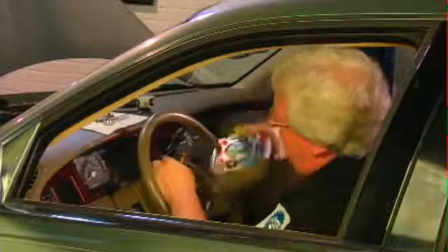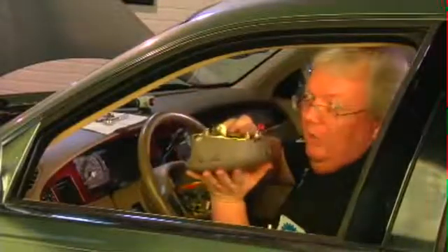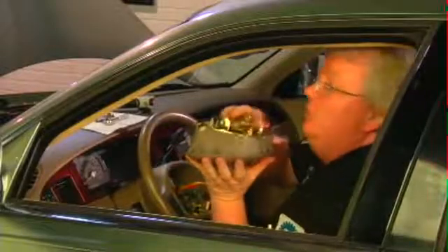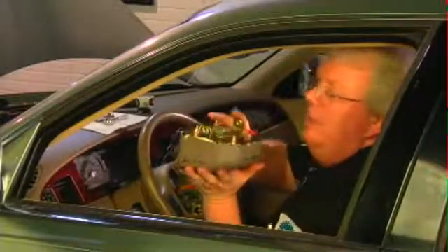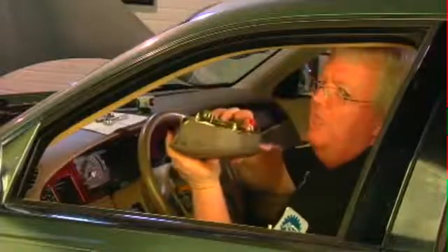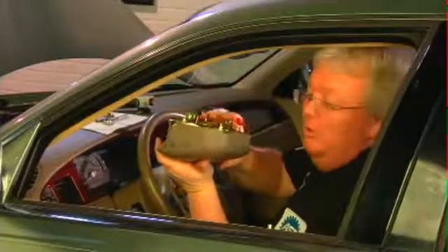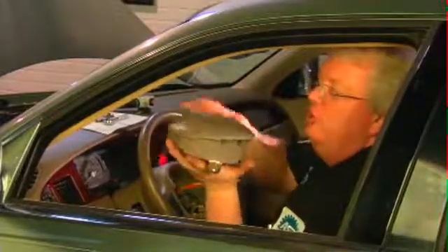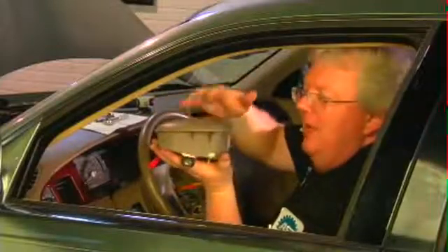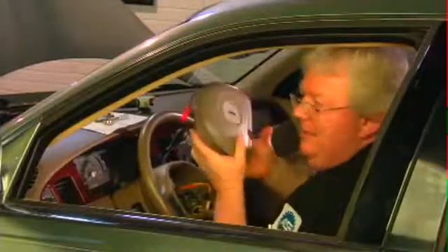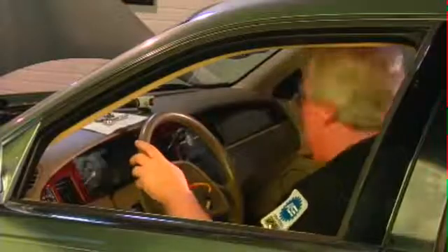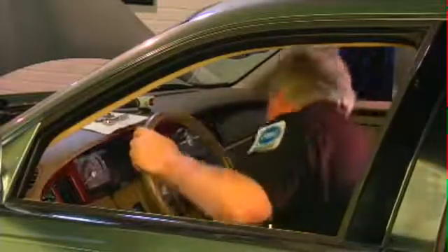There we go. So now the airbag assembly is removed. Do not set it like this on the table, because if it were to have gone off somehow, it's going to shoot up and whatever is on top is going to be damaged, and it could be you. So lay it with this, called the egress side, up, and it'll be a safe method of laying it down. I'm going to lay it right over here on the floor.